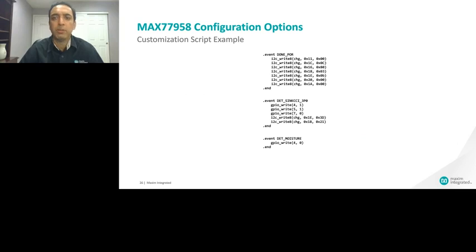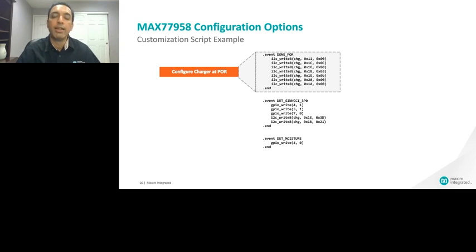This is just a very simplistic example, which of course does not quite capture the range of possibilities, but I just want to give you a flavor of it. At the very fundamental level, your device is going to power on, right? When there's a power on reset detected, you may want to configure your system for your initial state, whether it's to enable the charger in sync mode, or if you want to just maybe toggle an LED, you can perform all of those functions based on the power on reset event.